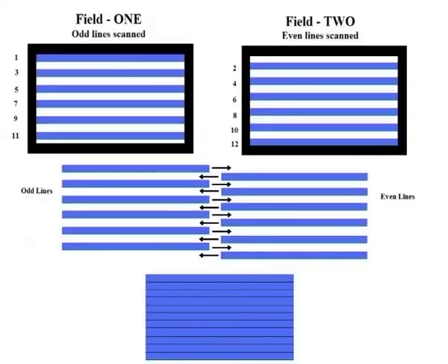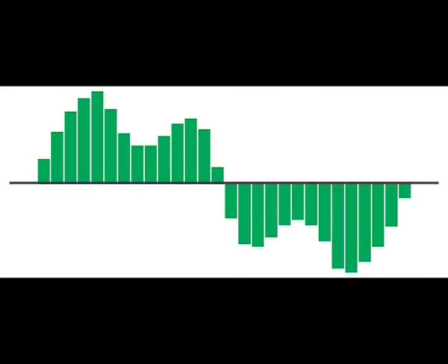It's important to understand the difference between analog and digital video. Analog video has a resolution measured in the number of horizontal scan lines, but each of those lines represents continuous measurements of the color and brightness along the horizontal axis in a linear signal that is analogous to an audio signal. Digital video signals consist of a discrete color and brightness value for each pixel.